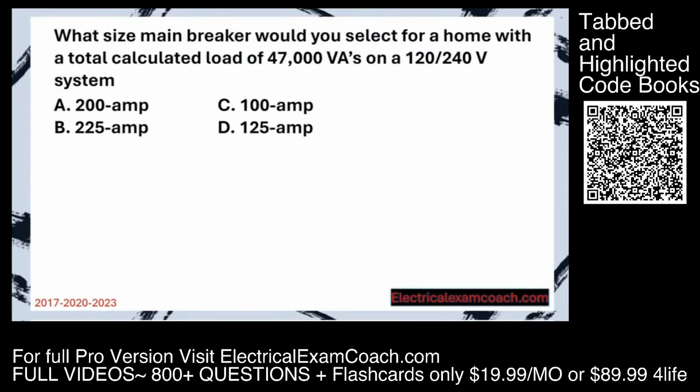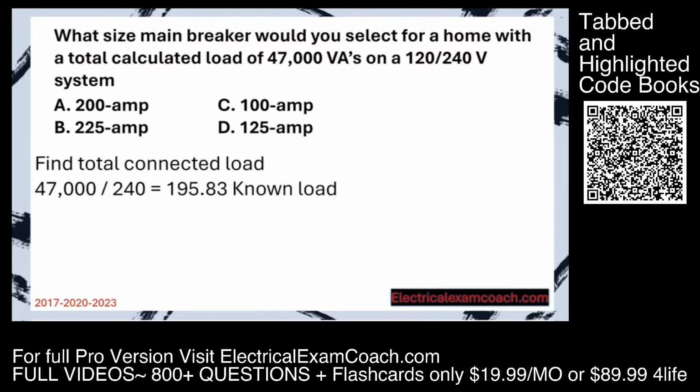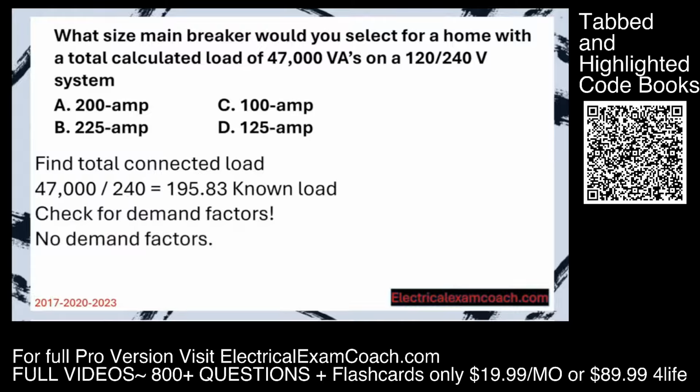What size main breaker would you select for a home with a total calculated load of 47,000 VAs on a 120/240 volt system? Step 1, find our total connected load. In this case, they've done all the math for us, and 47,000 are our total VAs. All we have to do is divide that by the system voltage. And in this case, it equals 195.83, and we would round down. Now we check for demand factors. And in this case, there are no demand factors because they were already performed to get us that 47,000.